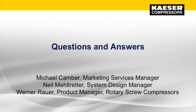Sure, it's a great question. In general, it really depends on the system itself. Larger industrial ones, I'd say definitely annually. Anytime you're considering new compressed air equipment is also a good idea. If you have a specific new CNC that's going in the facility and you want to know how much air you have in the system additionally, an audit is the perfect way to see how much air is available for this new use and to see if additional purchase of equipment is required.